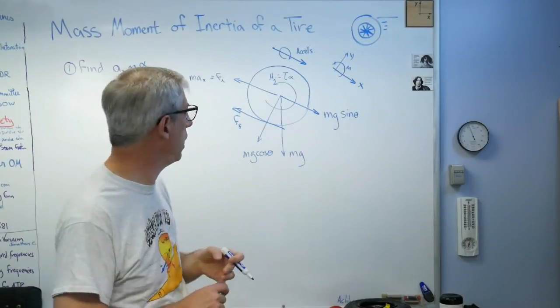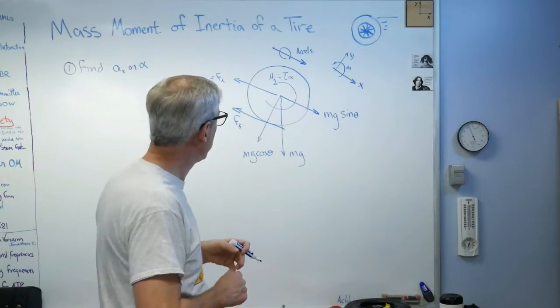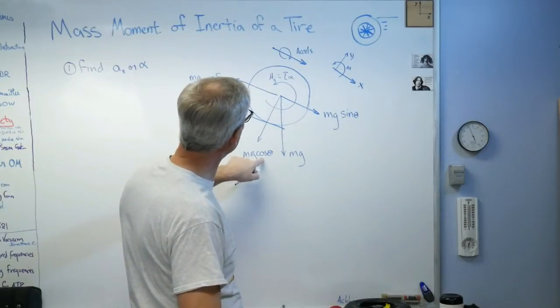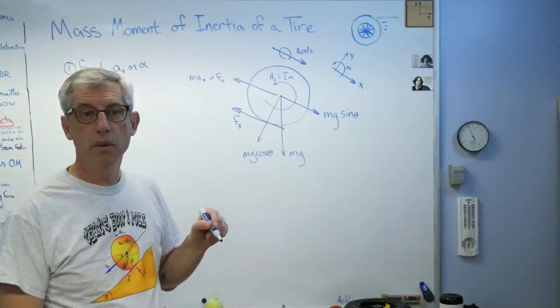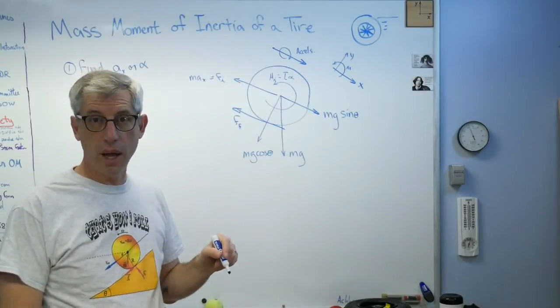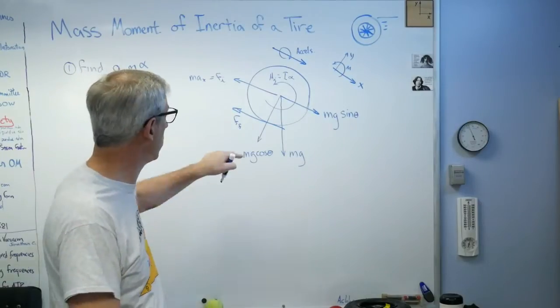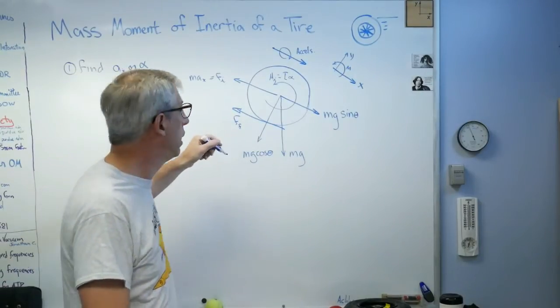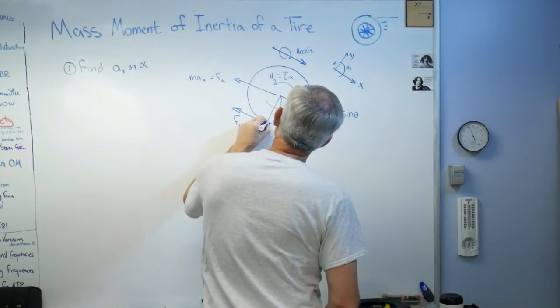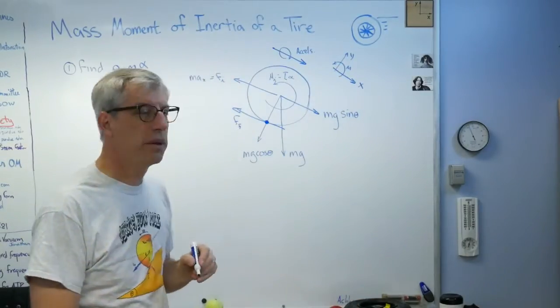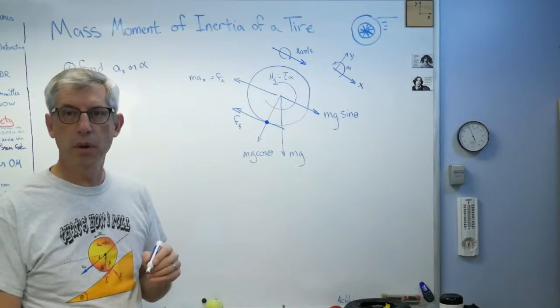Well, there's a lot of stuff I don't care about. You know, I don't really care about what that is, and I really don't care what that is. I'm going to assume that the tire does not slide going down the ramp. But as long as it doesn't slide, I don't care what that force is. So if I'm not going to care about a bunch of these forces, let's see that point right there. Okay, I'm going to sum the moments about that point.